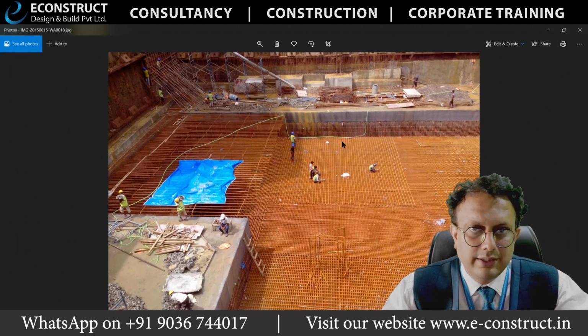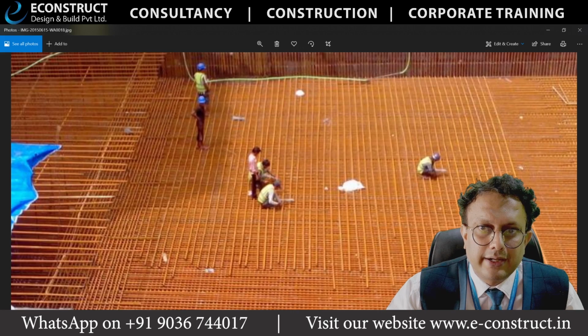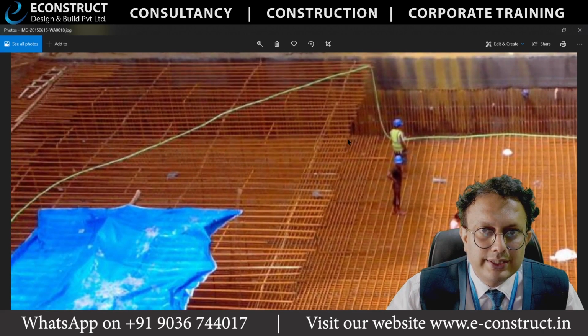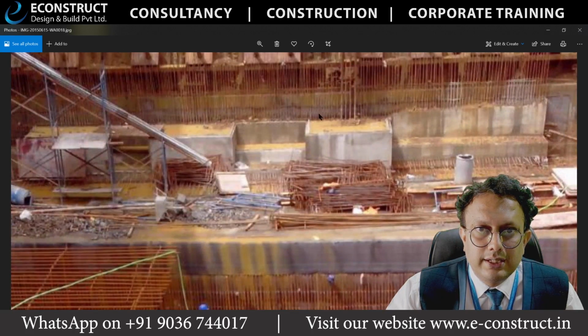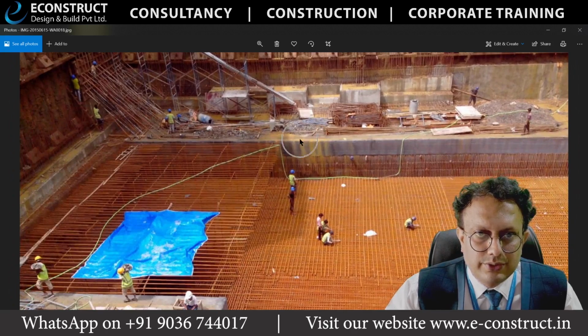Now let's go to the next one. What is this? You can see that these people are laying the bottom rebar, the second layer. The first layer is already laid, the second layer is getting laid. Okay, and simultaneously you can see that the people are starting the top rebar also. Understood? And what is this over here? This is the shear. This is basically the retaining wall. Retaining wall here, pedestal here, column here. Understood? So this is the bottom rebar, this is the top rebar. Yes. Okay, so let's go to the next one.